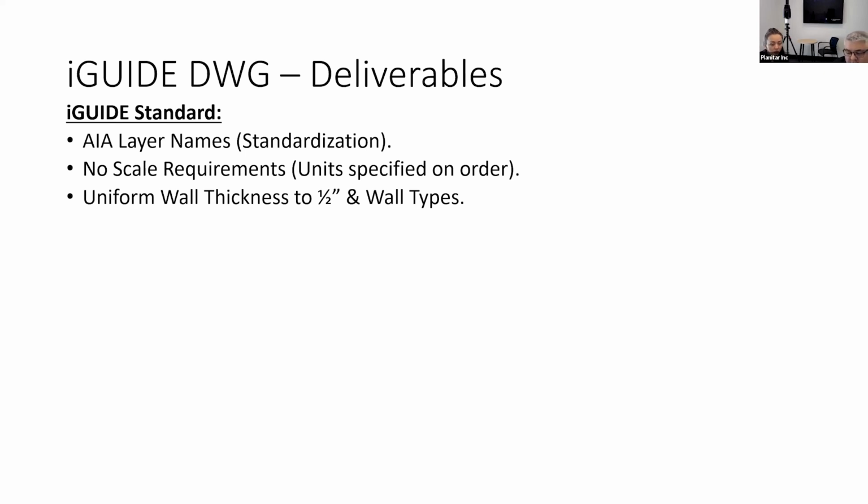Now across the board on the DWG file, we're making those wall thicknesses uniform, and that's really important when you want to go to the next step with your drawing, that you can rely that the wall thicknesses are accurate and have been rounded correctly. For construction or interior designers, it's just a uniform new baseline. There are no strange things that you have to correct.